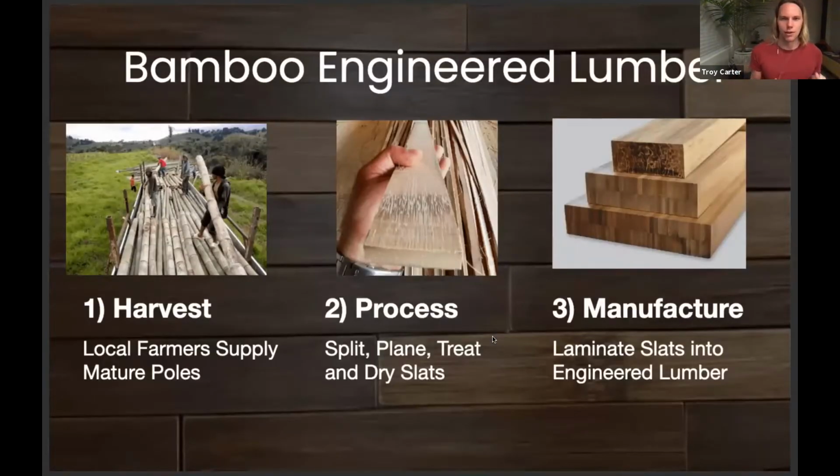So just a little bit about the process. You take really large bamboo. Most bamboo that's available throughout the world is moso or luang or other smaller species that are used for chopsticks, toothpicks, cutting boards, fiber, pulp, and paper. So we use Dendrocalamus asper, Giganteus, and Synechius, which are really large bamboo species. Four-side plane them into long, small boards and laminate those boards into pretty much any size or shape that our customers demand, whether those are panels like plywood or boards and dimensions for structural uses.